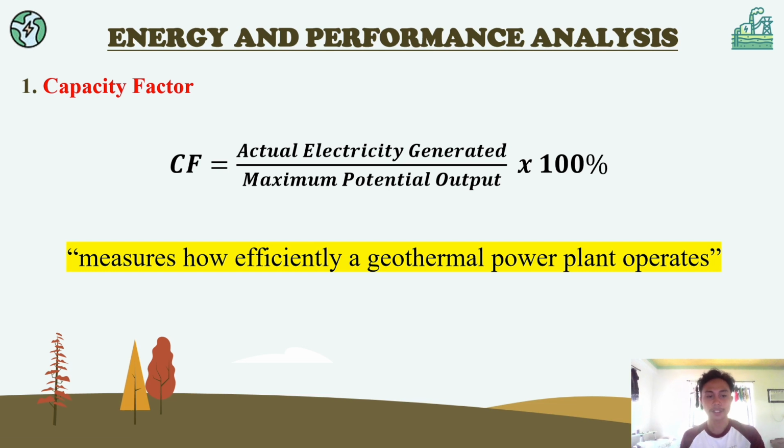Capacity factor measures how efficiently a geothermal power plant operates. To calculate it, the capacity factor is equal to actual electricity generated over the maximum potential output times 100%.